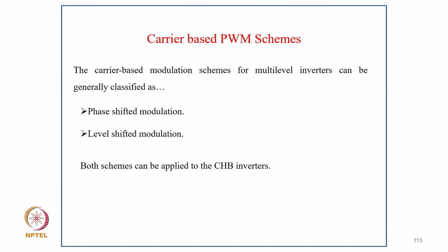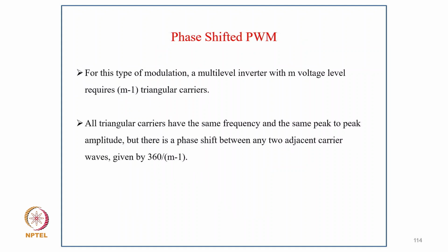Now coming to carrier-based PWM techniques. The carrier-based modulation schemes for the multilevel inverter can be generalized and classified as phase-shifted modulation and level-shifted modulation, and both schemes can be applied to the CHB inverters. Now coming to phase-shifted PWM.